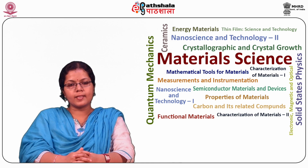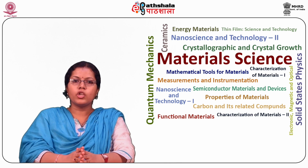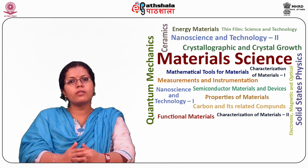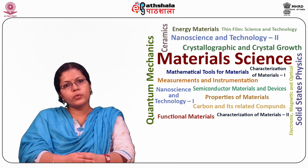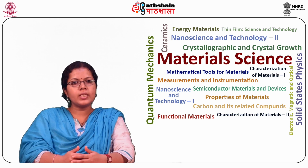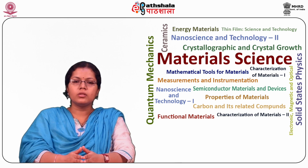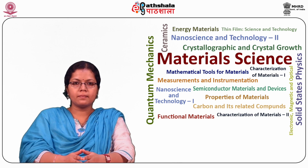Old style magnet systems consisted of a relatively long U-shaped permanent magnet having soft iron pole pieces. Owing to development of materials like Alcomax and Alnico, which have a high coercive force, it is possible to use smaller magnet lengths and high field intensities.